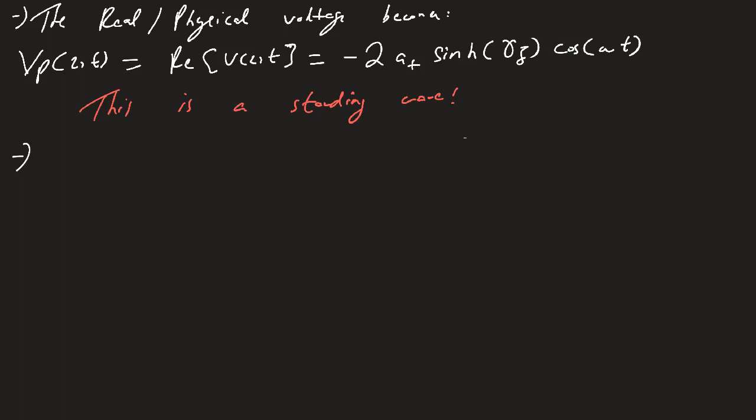We've looked at a standing wave in a short circuit condition. Let's now go to the next case, which is the case of an open circuit, and see what happens. So we will now do case 3, and I'm doing these cases to just give you an idea of these reflections. Case 3 is that the load ZL is infinity, and so we basically have an open circuit.